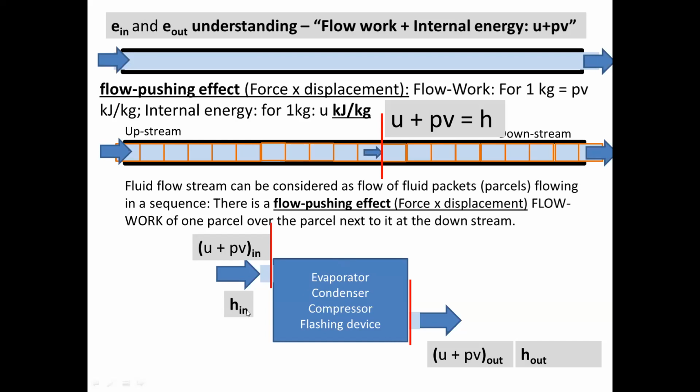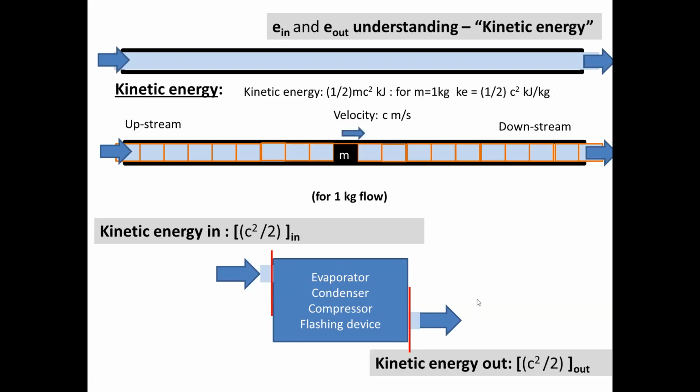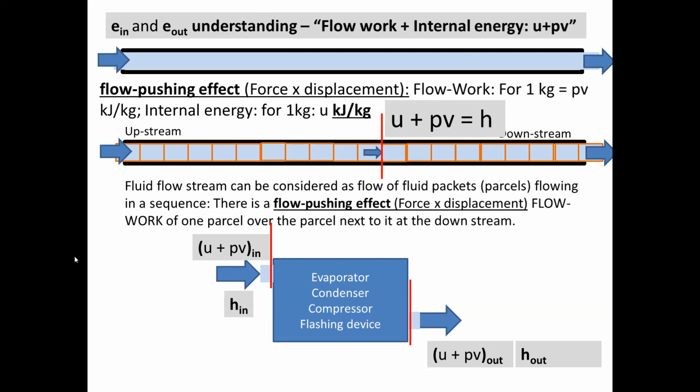So this can be the control volume. In this control volume, entering flow contains the internal energy plus. When it's entering, this fluid receives this flow work as well to push this flow into the space. Same time, push out here as well. So very important.